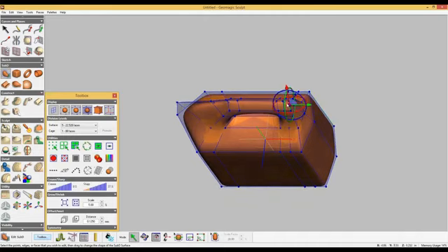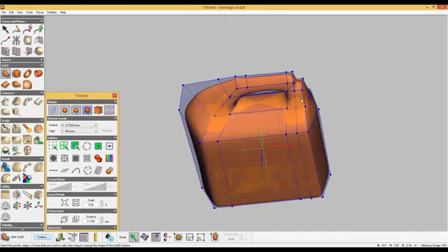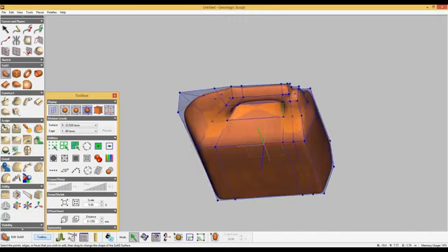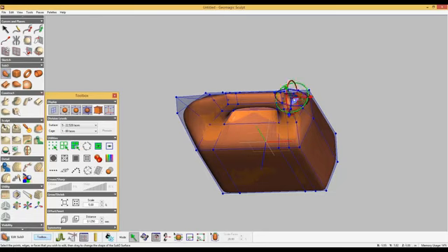For a stepped contour at the back, grab the Select tool again and select the back 3 edges behind the handle. You can hold the Control key for a multi-select. Click Delete and make whole. Select and extend the back edge and smooth by changing Sharp to 0.